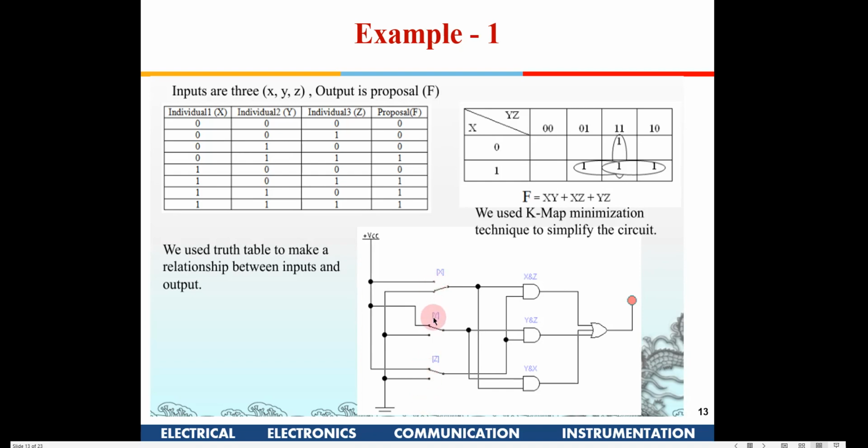At any given point of time, the inputs will be either 0 or 1. It will not be hanging, like no connection at all. That kind of thing we should not do with digital gates, because if it is hanging, you are not telling the gate whether it is 0 or 1, it is just hanging. So hanging not necessarily means 0. You got to understand that.